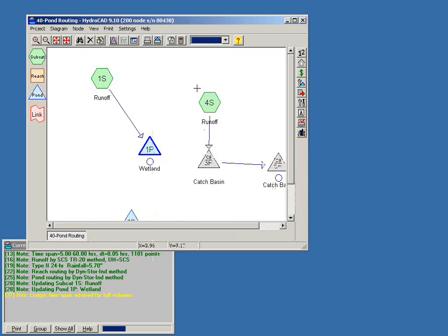And what you would typically do to get there is that we would usually model our existing scenario first, and use that to determine the peak discharge from our site. And typically that is all you're allowed in the developed scenario, or perhaps you're allowed 110% or 90% of that. Whatever it might be, you'd use the existing scenario to determine your permitted discharge. You would then go to a model for your proposed situation with your proposed watershed, and you'd generate the runoff hydrograph from that proposed watershed.